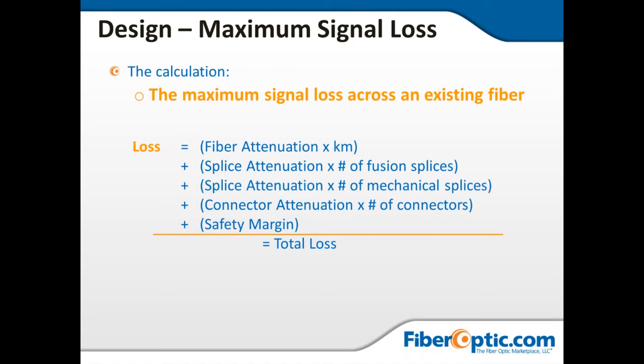Now the components themselves are pretty much not wavelength specific. So the second item that we have here is what's the splice losses. Normally this is a budget, and for inside plant people, if you're doing pigtail splicing, the EIA recognizes 0.3. Well, 0.3 mechanical splice or fusion splice, although we all know that really wouldn't be acceptable for a fusion splice.